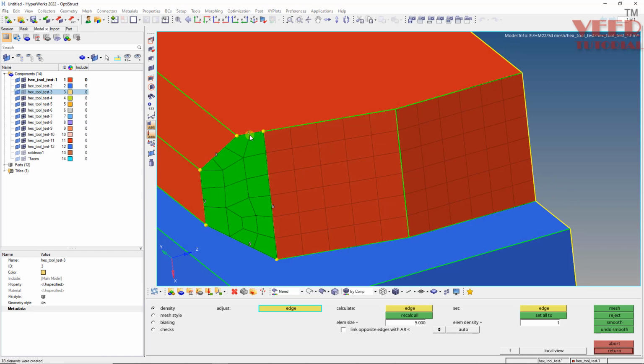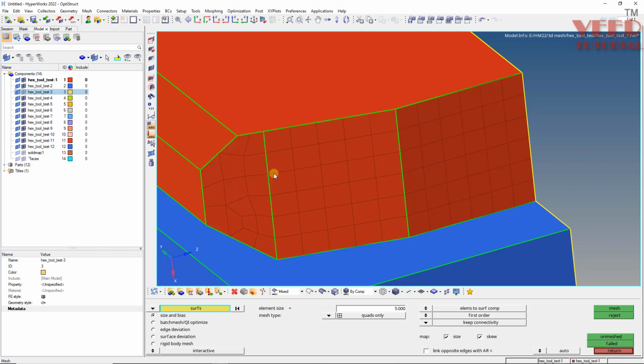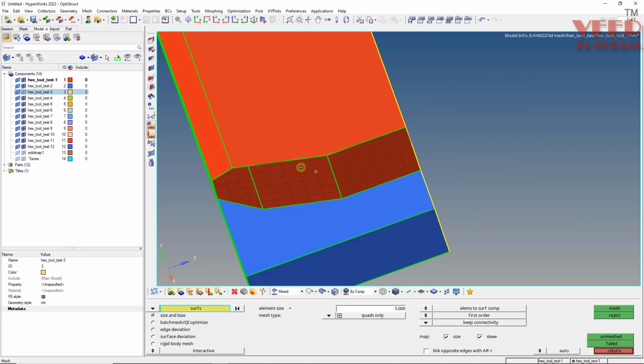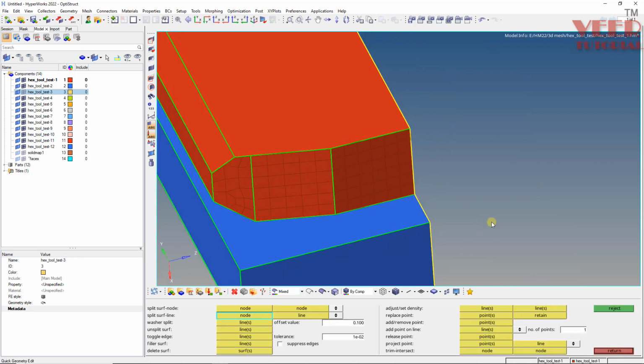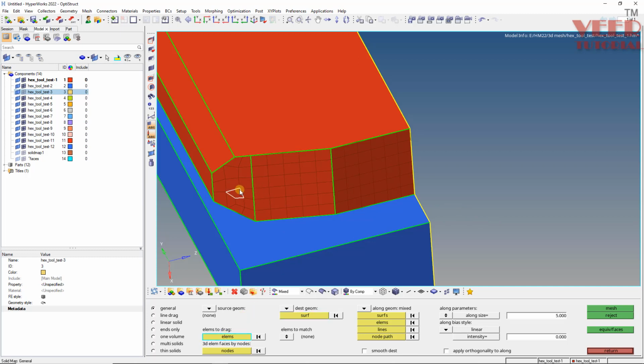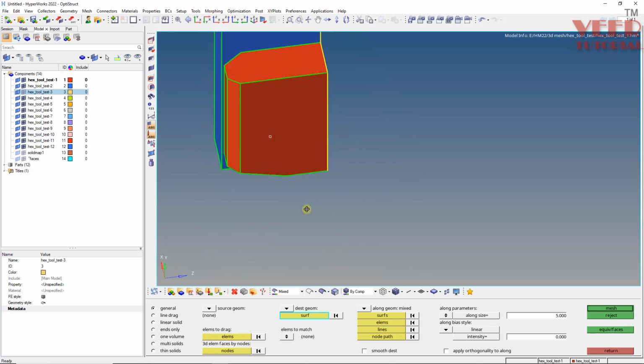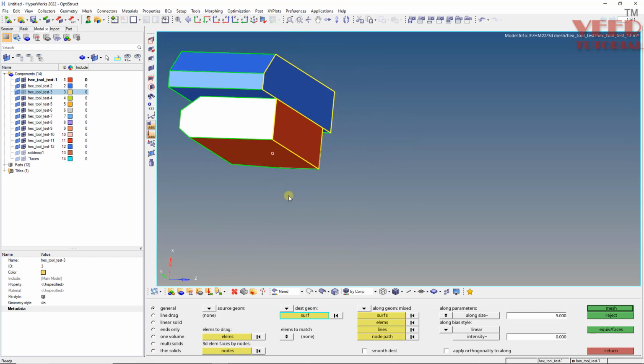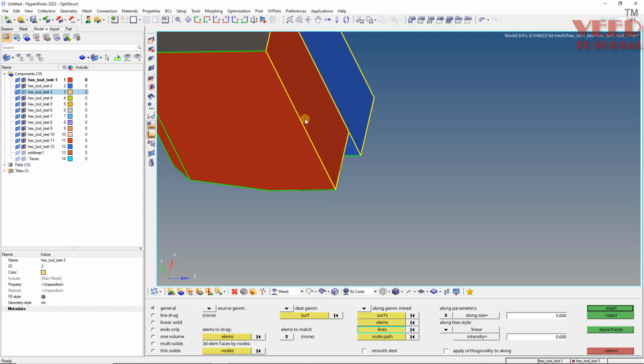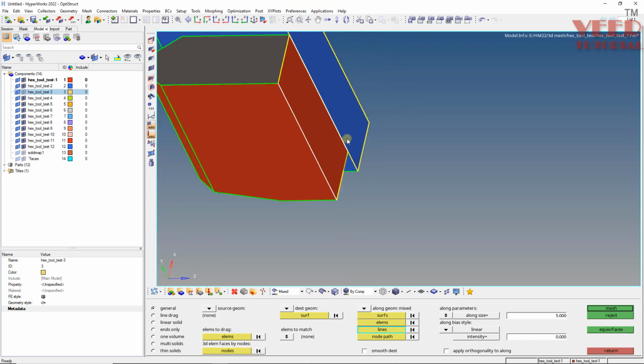Let's say make it 2 and again make it 2 here. So there are some ways you can change the mesh flow. Okay, right now you can see there is no tria. So the mesh is done here. So after that I can go to this solid map, press Z, then element and select this element by face. Destination should be top. Then in the guiding I will select lines. So this line and this line. Okay, not this one.